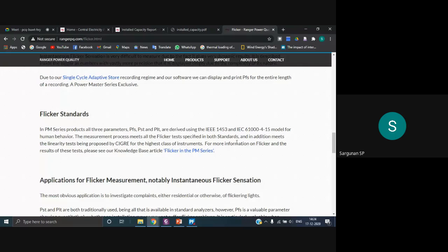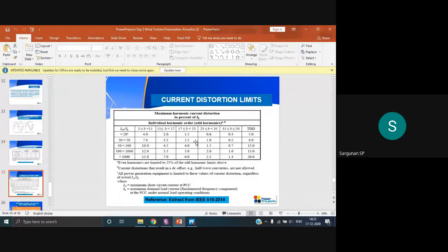Okay, so for the IEC standard, you can see it comes up with different parts. It ranges from 1 to 12. The different parts speak about different things. For example, part 3 generally speaks about the measurements, how we are going to measure things. Similarly, part 4 will give you the things which have to be maintained, or the required limits in the system. So if we examine part 4, you'll be able to find out what flicker has to be maintained. Normally this value ranges depending on the kV, as I showed similarly for harmonics. The flicker also varies depending on the kV ranges.